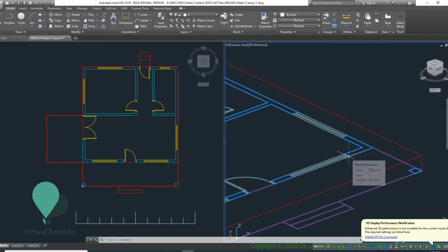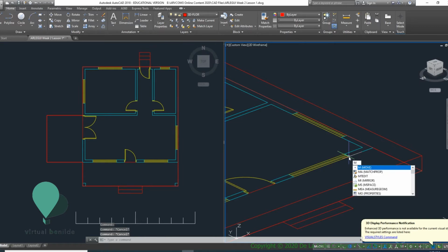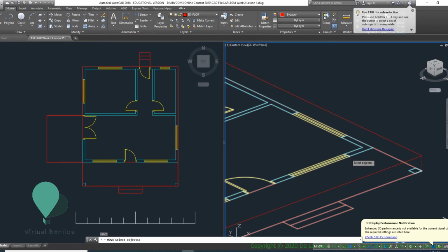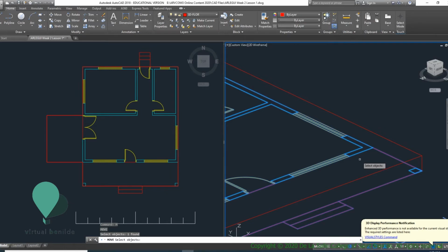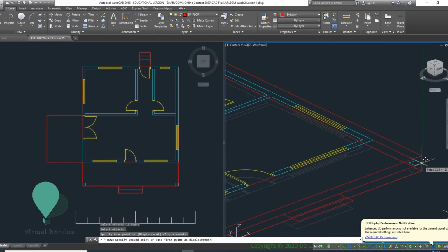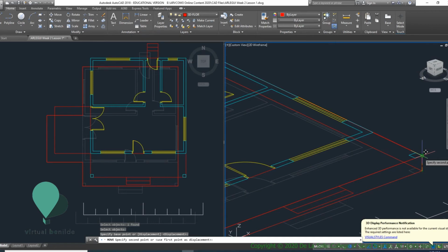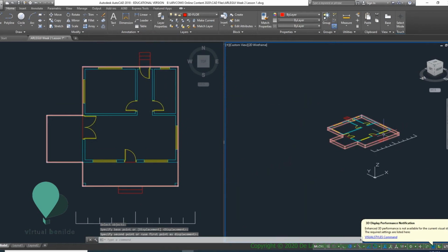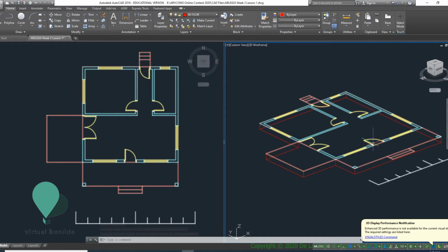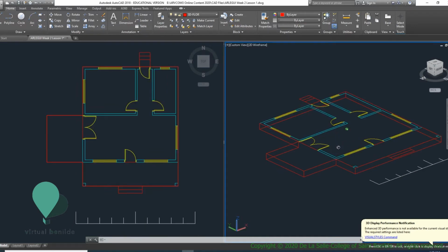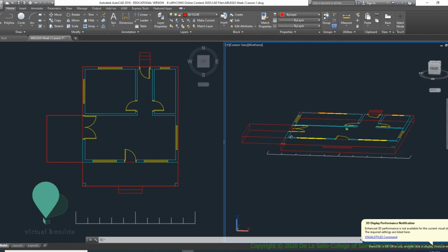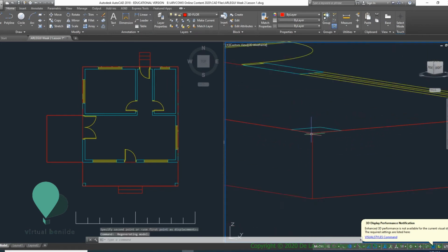I'm going to move this floor plan block. M is the shortcut for move. Click onto which object you want to move, enter once. I'm going to grip it here because that's the 0 level of the floor plan, and raise it up until it clicks to that 0.45. To check that the floor plan is in the level, you can rotate and orbit, and you can see there's no gap, no spaces.